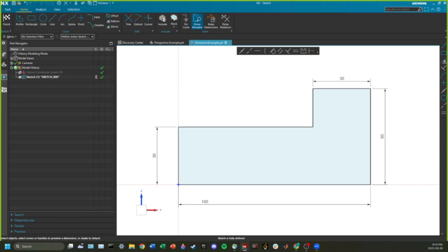Rather, from doing this, I'd say from the origin, go 70 over and start your cut. That way, the same point is always in reference, and when you have it on a mill or something, you can go from there and you start making your part. Whereas if you had to make cuts in sequence, that line is now in reference, and you have to make the other ones first, which isn't always advantageous. Sometimes you want to start with the 30, but you can't because you're reliant on the other parts before it.